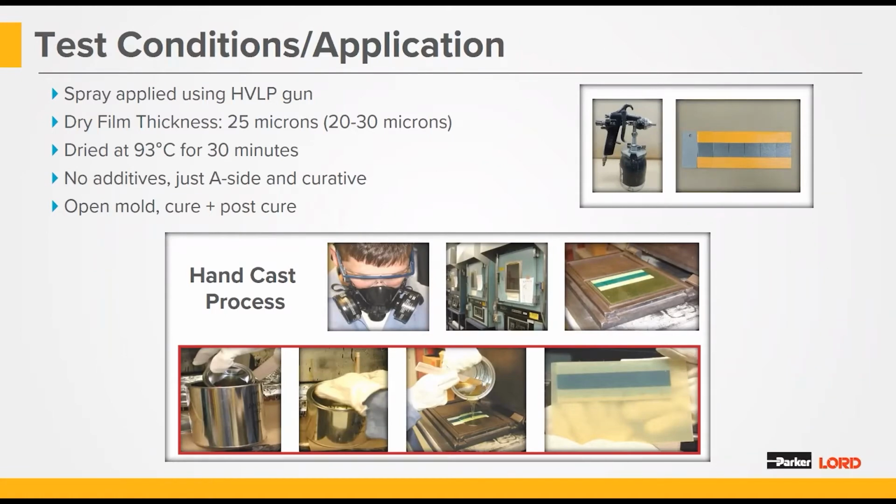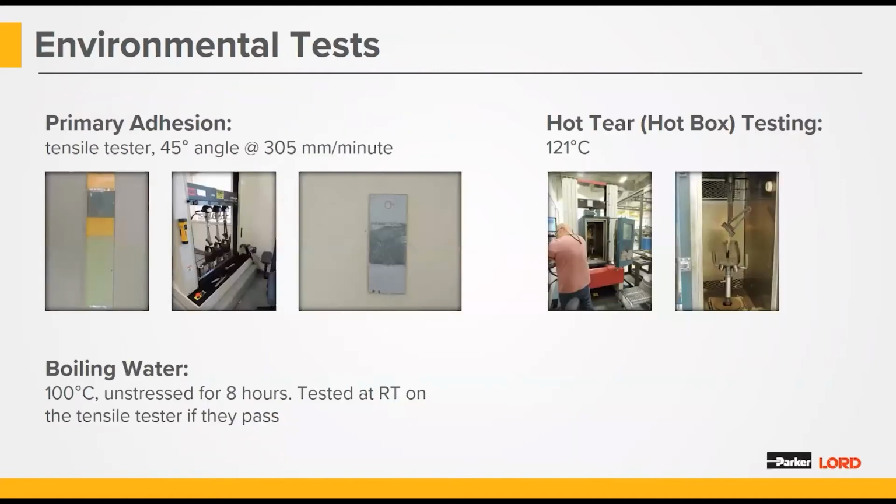Now, this plaque has to undergo a post-cure in order to develop full properties. After that, we did environmental tests. Primary adhesion on the tensile tester, 45-degree angle at 305 millimeters per minute.